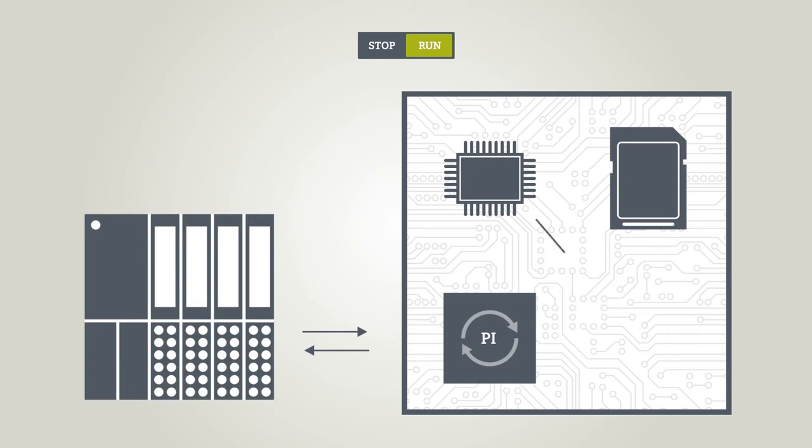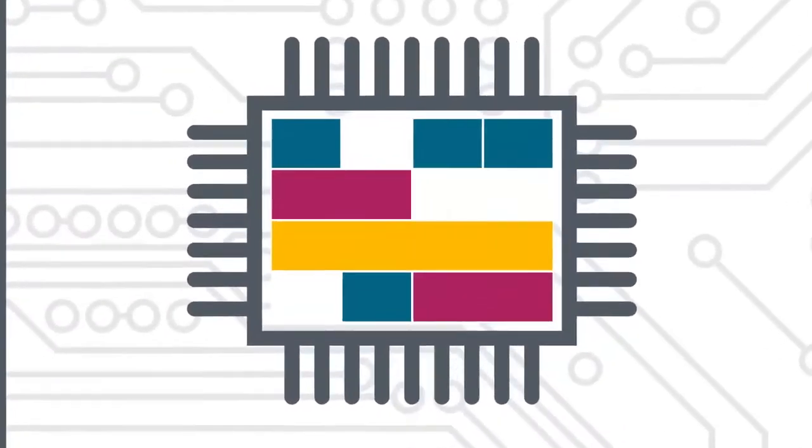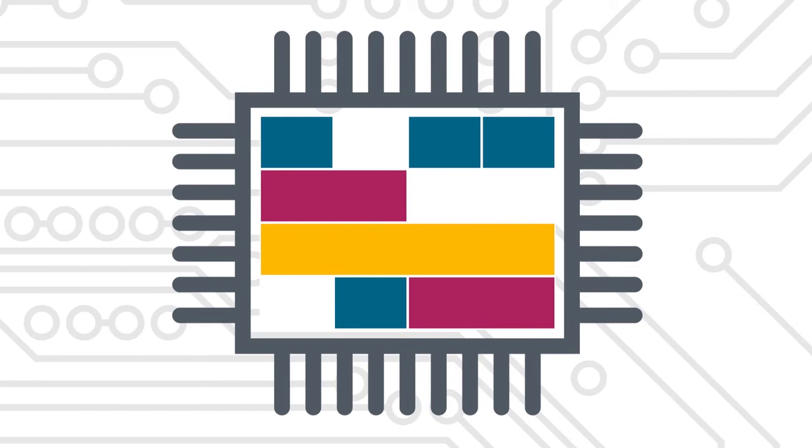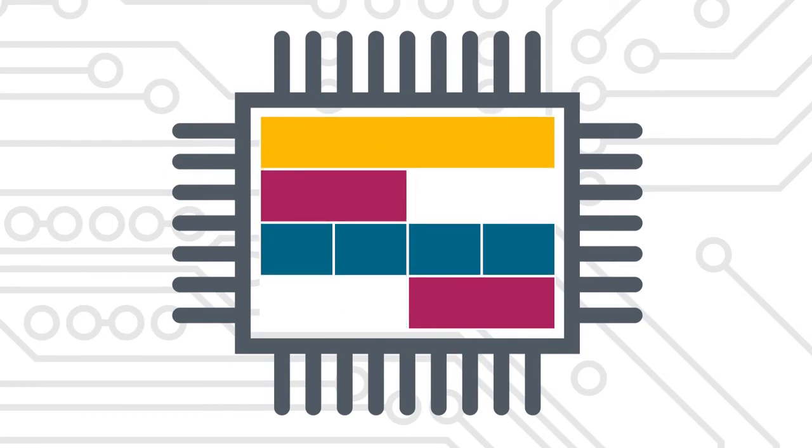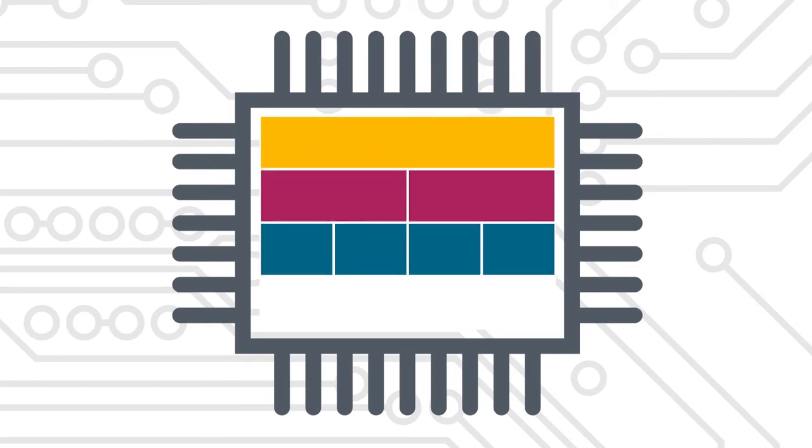Important data is written to the embedded retentive memory when the controller is set to STOP and will be available again at the next startup. You define during programming which data is to be handled as retentive. The SIMATIC S7-1200 and 1500 controllers have an optimized data filing system. This system significantly reduces memory requirements and access times.